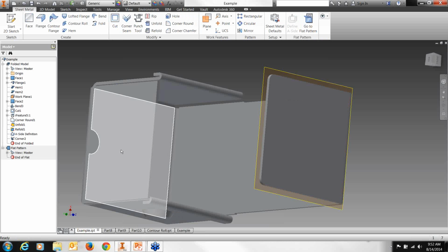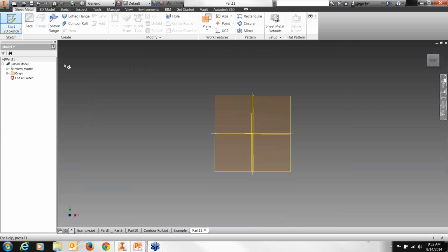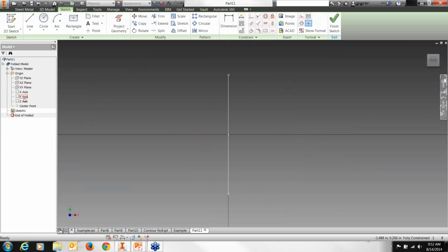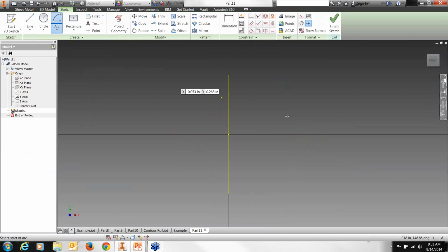Some more coming in here. Can we show a semicircular rolled sheet? That could be performed with the contour flange. You can draw out the radius of your vessel, and then use the contour flange to extend that and show the depth. Let me go through that, actually. They want to create a semicircular rolled sheet and then show the flatten of it. Throw an arc on there and use the contour flange to show the shape and the depth of it. And then to change the thickness, change the rule, and so forth.